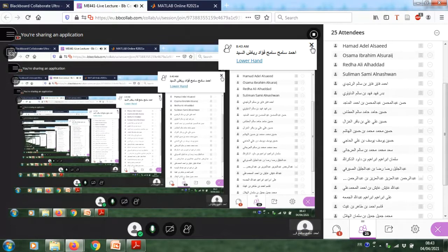You can use the Routh-Hurwitz criterion, I mean you complete the table and prove that it's stable, or you can just find the poles. If all poles are located in the left half plane, you can say that the system is stable. You can use the calculator and find the poles, or you can use the Routh table.